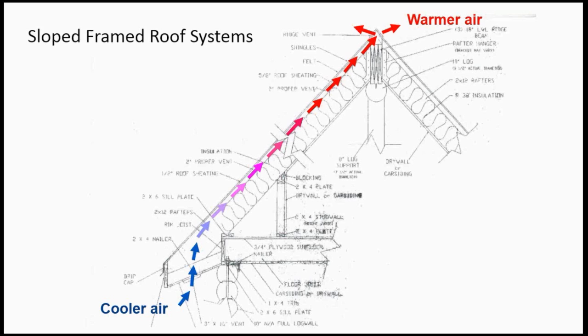Cold air is dry, even if it's 100% saturated, because it just can't hold very many grains of moisture. So as that air comes in and moves through the roof system, it brings that cold, dry air, it warms up, and if there's a little bit of leakage of air from the interior, it is dissipated by that airflow.